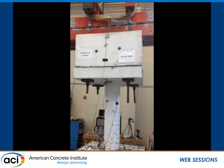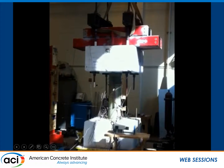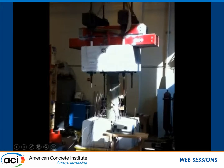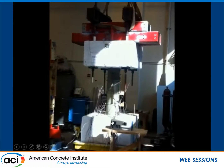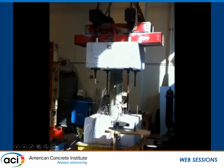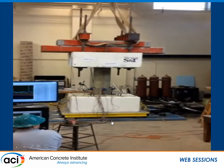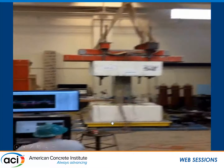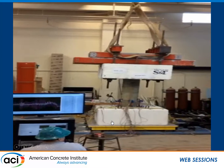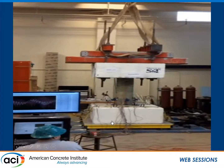This is the one with the rubberized concrete, the segmental one without energy dissipation. So you see it's more flexible. If you look over here, there's an opening and closing of the joints without really any significant damage. And you will see more quantitative numbers on the next few slides. It's the same column, but for some reason the video here is very distorted, but the same height, everything is the same. This is the one with the energy dissipators over here.